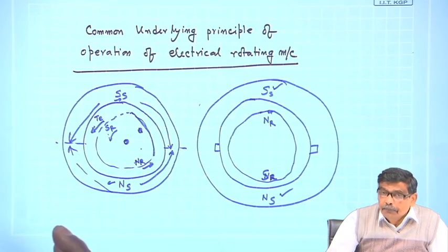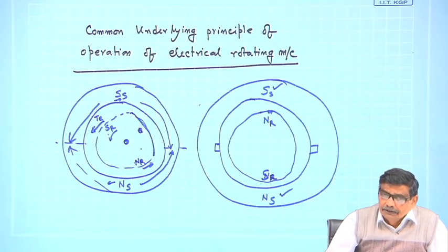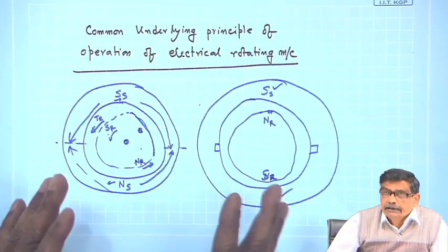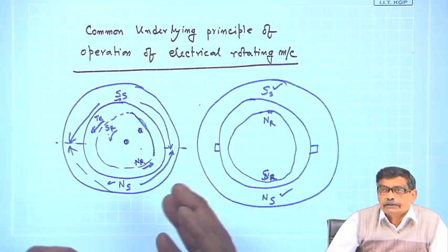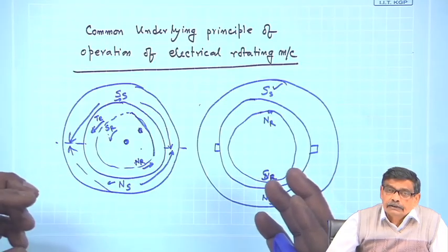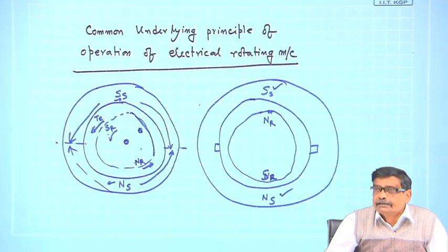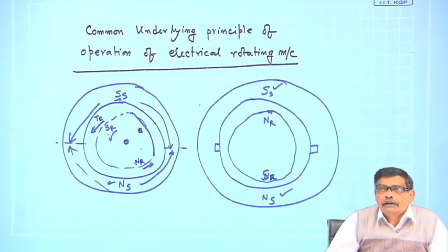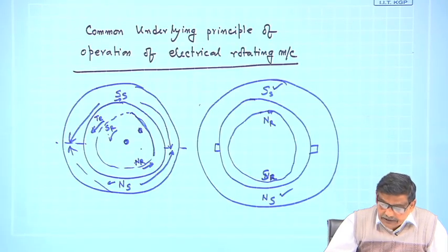But the important point is, we will see later that even if coils are stationary, they will carry some current and still can produce poles which will be found rotating. That is a great achievement, and it was first pronounced by Nikola Tesla. That is, even a stationary coil can produce a rotating magnetic field. So, let the rotor move, that rotating stator field will also move, such that the angle between these two will remain constant and give you sustained torque.